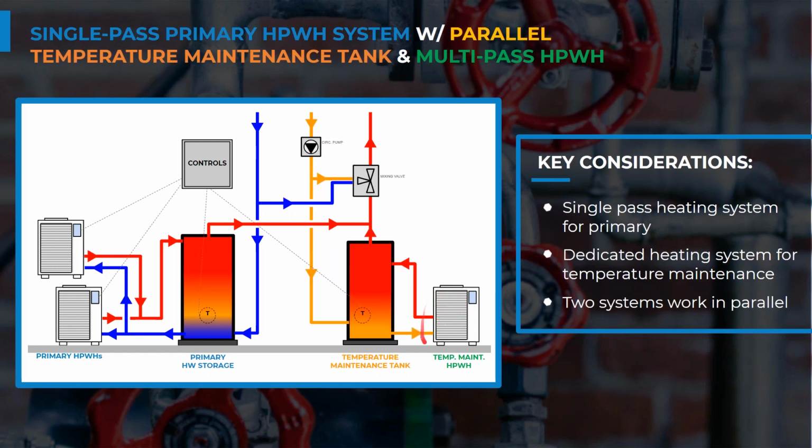And that heat pump is typically configured in a multi-pass heating cycle so that we have an unmodulated flow rate through this unit, and we're just trying to put as much heat into it as we can through each pass. And so that heat pump is going to take in that typically 110 degree, 115 degree water towards the bottom of our tank.